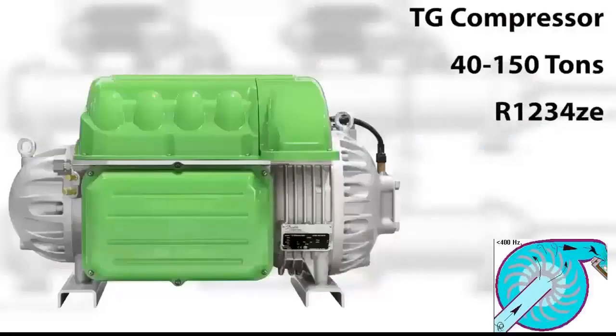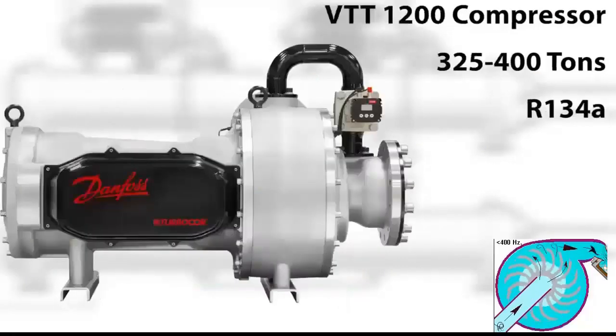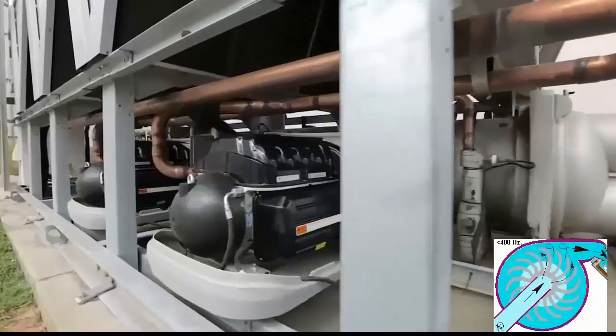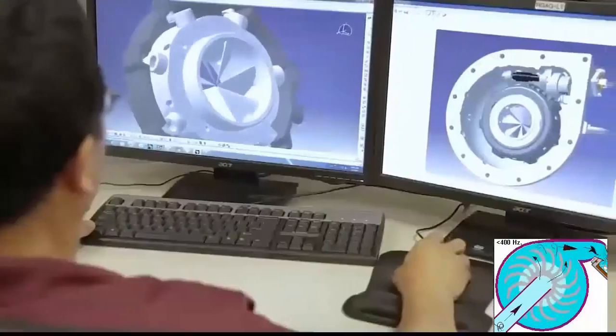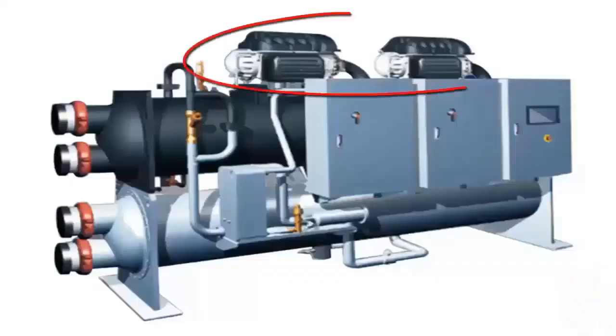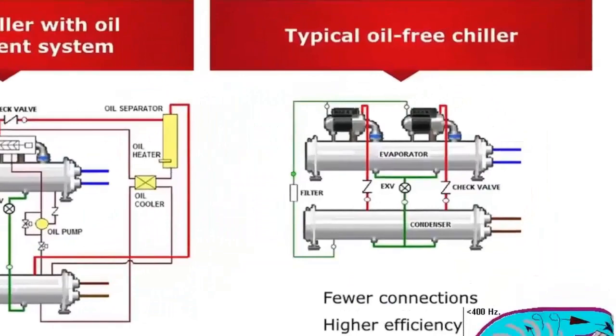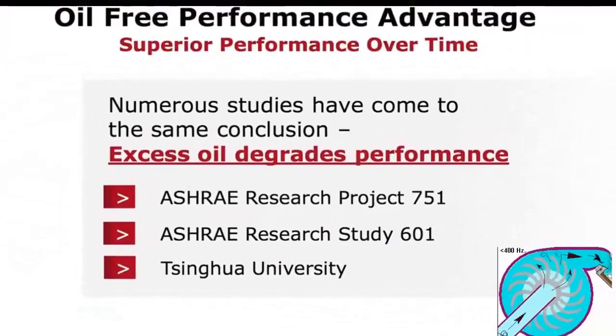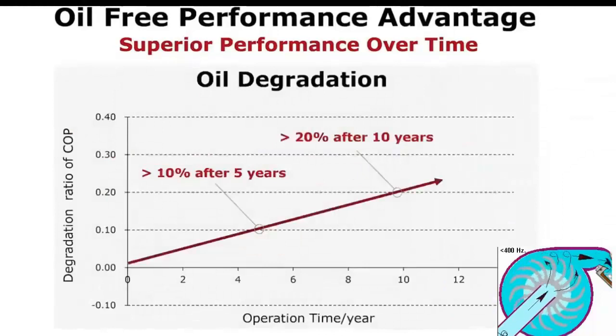These centrifugal compressors generate quite a large saving, especially when the bearings are oil-free, which is the technology that is currently being used. When the bearings are free of oil, the performance increases even more because, firstly, we are not going to need a lubrication system in the compressor, and secondly, there is going to be no presence of oil in the exchangers. That will also increase the efficiency of the machine.